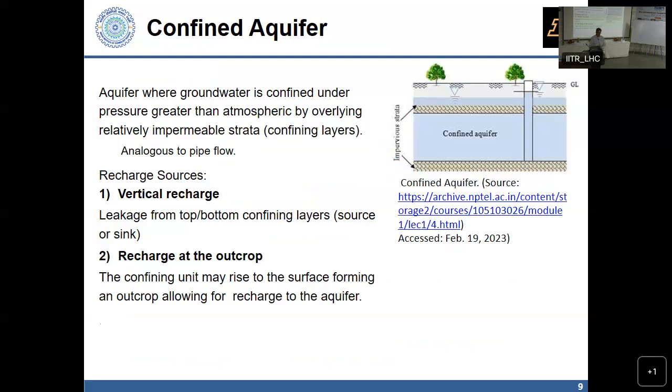This will become important when we talk about groundwater flow. When we say it's essentially two-dimensional flow, we are saying we are using wells which are spreading throughout the aquifer. What we are measuring is something that is effectively throughout the thickness, and we will focus on horizontal flow. But the height to which water rises in the well, therefore, gives us an estimate of the piezometric head. Yes. Suppose if it is a partially penetrated well, right, then the pressure will be different.